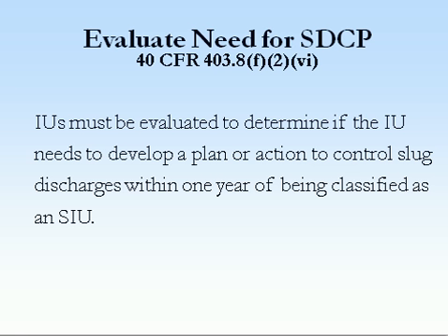If you determine that they do have that potential to slug you and they need to have a slug control plan, at the top of this slide, the reference there, 40 CFR Part 403.8(f)(2)(vi), is where you can find more information about what needs to be in that slug control plan.